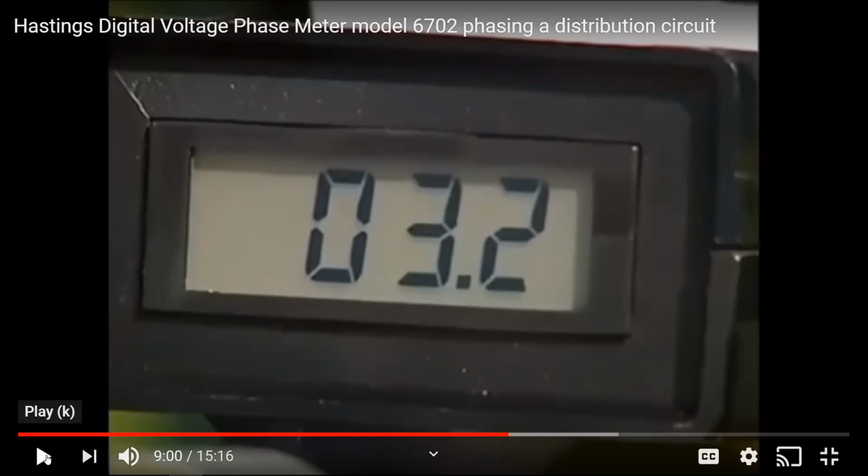He's doing the same thing exactly here, except now it's on the conductor. That's why he's called it a bolted fault. The center of the primary conductor is making physical contact with ground, and he's unable to charge the cable. He's always introducing 3,200 volts DC onto the conductor. This is not going down, so this is what they consider a bolted fault.